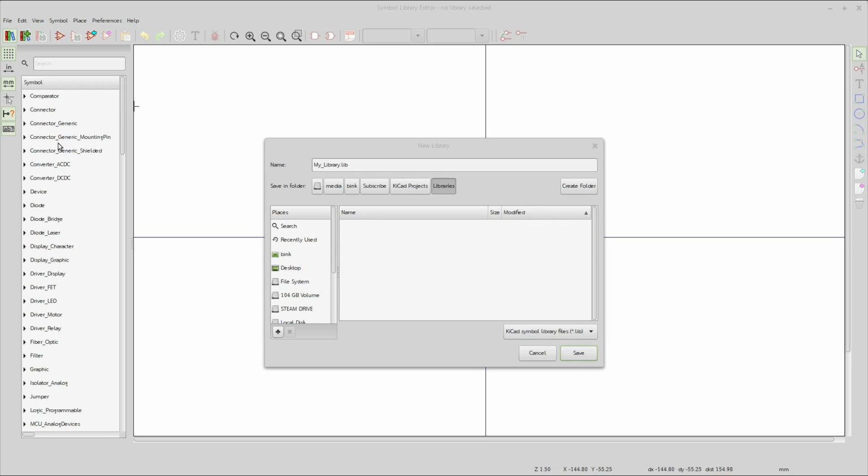You'd go over here to the side, pick it, and hit the little arrow, and it would expand out, and you might have 100 or more symbols inside there, and you're scrolling and scrolling looking for an IC schematic or something, right? Well, maybe you make one library called ICs, another called power, and another called passive.